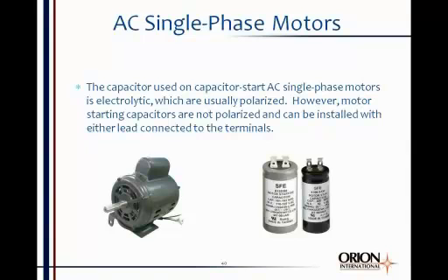Okay, the capacitor used on capacitor start AC single-phase motors is called an electrolytic type of capacitor. Usually electrolytic capacitors are polarized. They have to be put into the circuit in the right direction, positive and negative. However, motor starting capacitors are not polarized because it's an AC waveform that's going to be passing through them. And you can put them in either way, with either lead connected to the terminals.